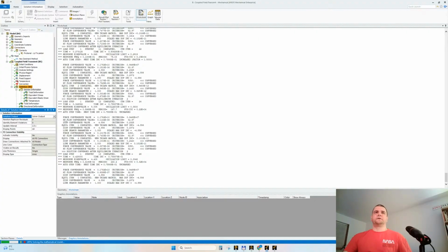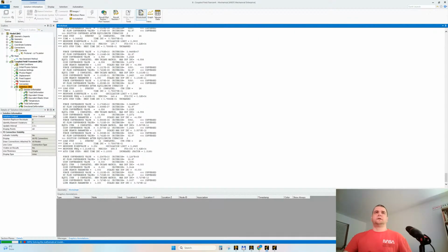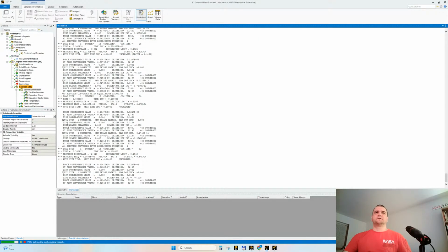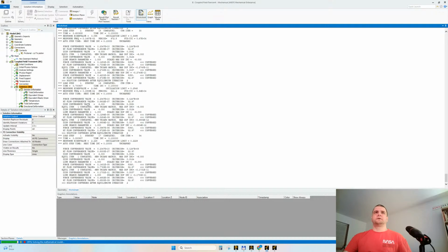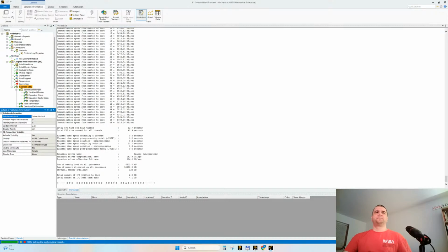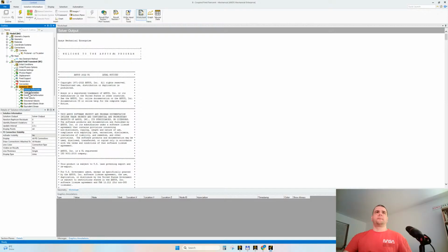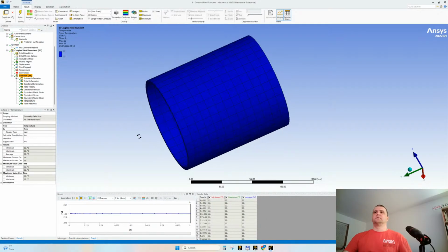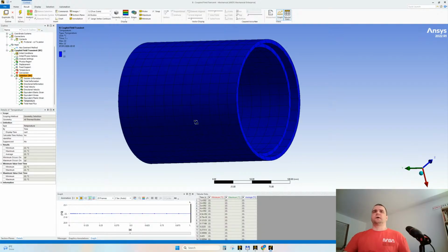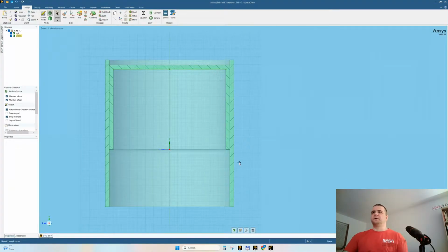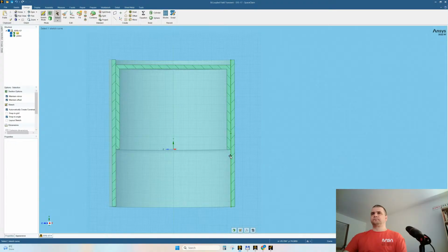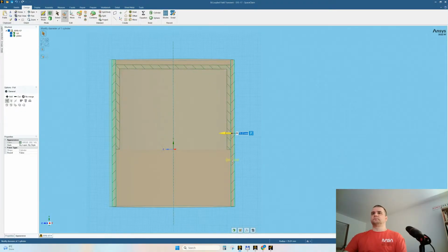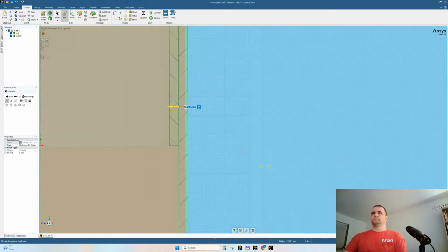So we can look also here. Heat flow convergence, displacement convergence, line, such parameters. Yeah, everything looks nice at this moment. Let's see. Oh, nothing. All right, so let's decrease the gap even more. 75.001.